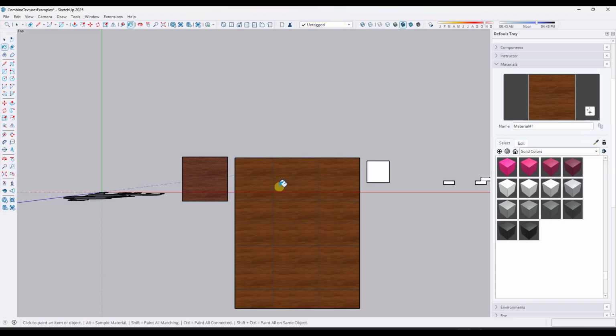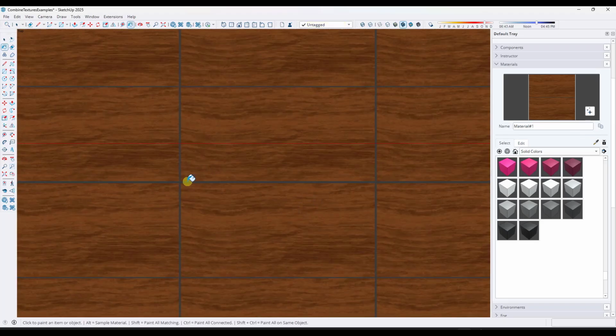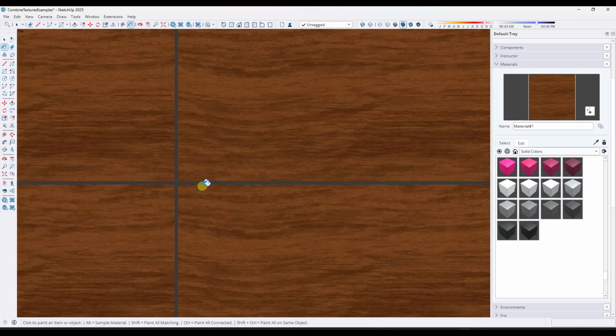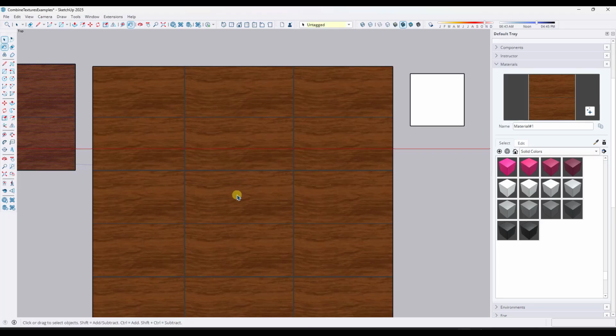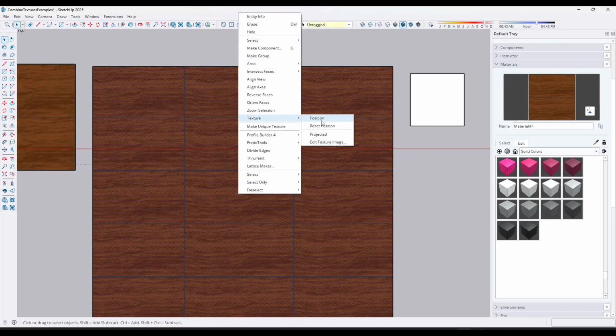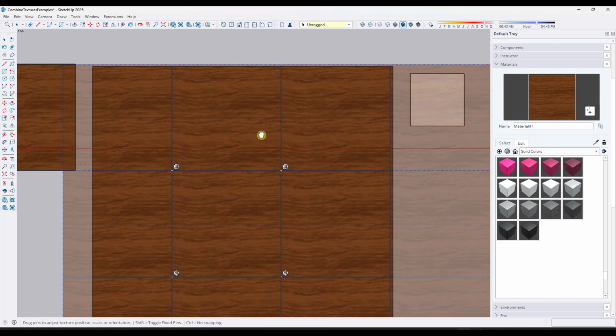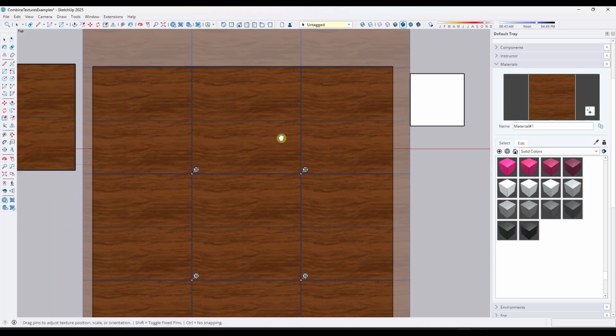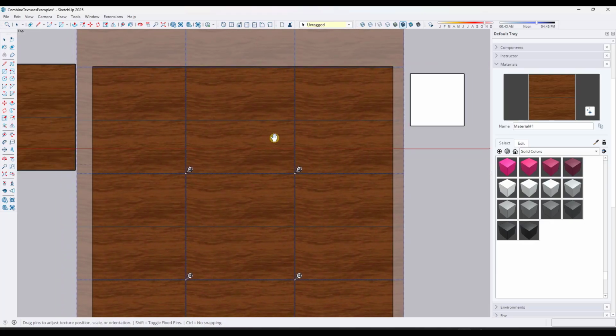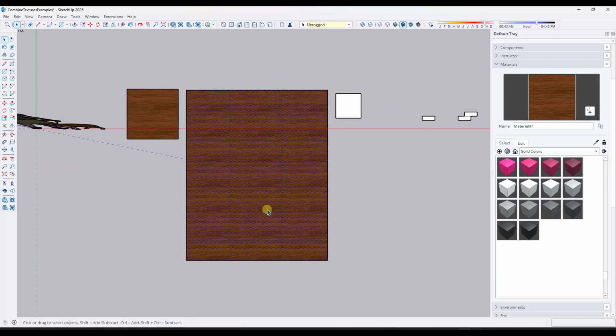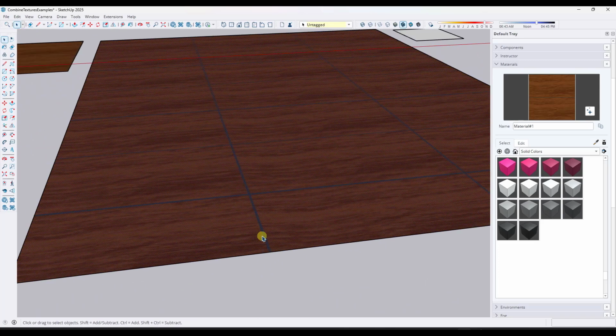well, if I select this object and apply this to the surface, notice how now I've got the image with the gray material in between those panels, just like this. And it's actually in here as a texture. And then we could use Position Texture in order to move it around to make it sit on the face or whatever we wanted to do with that. But this is a really fast way to create these more complex shapes, and I don't have to recreate this geometry over and over again.